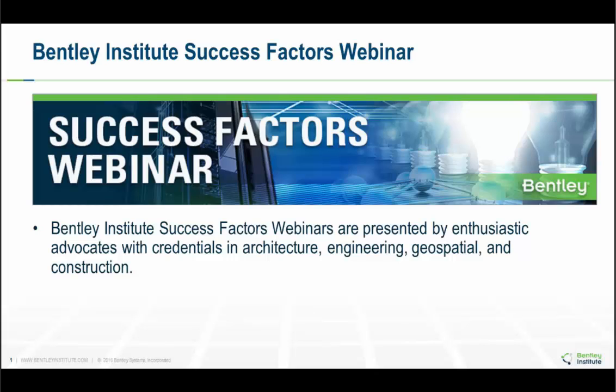You need to use factored loads because in the design they need to have the effects of being factored. The alternative is when you do an iterative analysis, you should be doing your iterative analysis on factored load combinations, and your iterative analysis needs to be done on each combination.